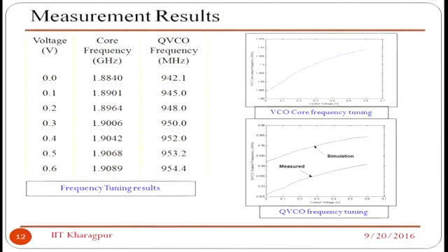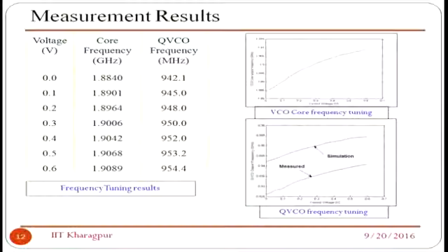So that's why you have those kinds of controls. A 4-bit control is there. So it is called the free running frequency. If you design for 1.8 gigahertz and it is a little less than that, don't get worried, because you have fine tuning. So you can always tune it to the free running frequency. So that is one approach I should tell.